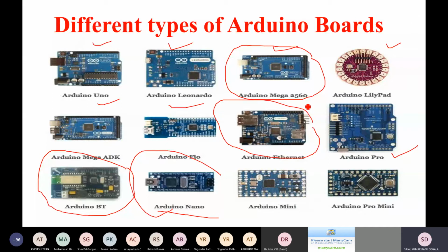If you purchase the cheapest boards, then you have to use drivers apart from the drivers that you get with the Arduino IDE. If you purchase other boards at a low cost, you are not going to get any issues. But if you purchase the Nano at a low cost, you are going to get issues with the drivers. Your PC will not be able to detect the Nano. So try to consider it.